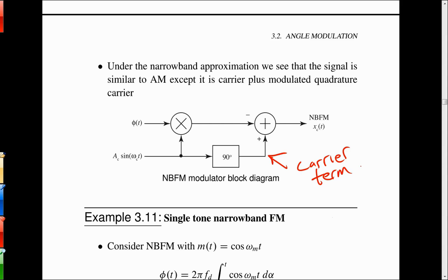And it's really no surprise because we're using a sine carrier and a cosine carrier, but there's no other terms in that. It's just that it's done with FM, and the fact that it's done with FM is also telling you that it's maintaining that constant envelope behavior approximately too. And you can demodulate it taking your choice of techniques, usually with something called the discriminator that we'll be talking about.